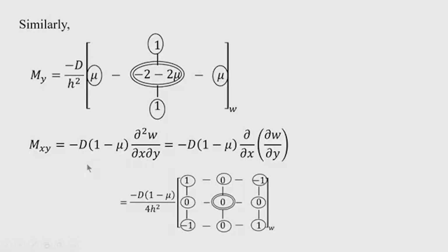Later on Kirchhoff modified this condition and gave two expressions instead. So m x y is combined with the shear force Qx or Qy to give one effective shear, Vx or Vy. Therefore the m x y expression is also needed for calculating the effective shear value.